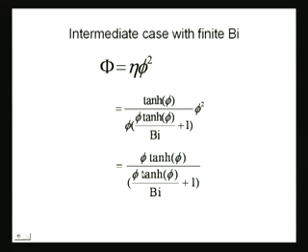So you will get Biot number over phi. Just by, I think, no, sorry, we are looking at the observed Thiele modulus. So if you look at only the eta, then you will have Biot number over phi squared, right, phi squared, yeah, Biot number over phi squared.